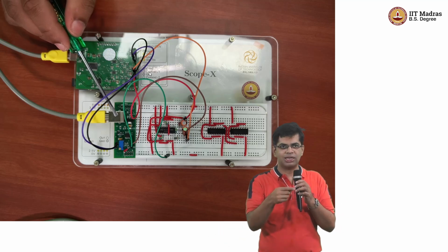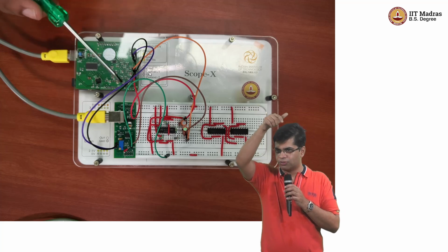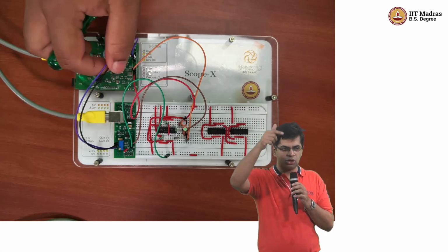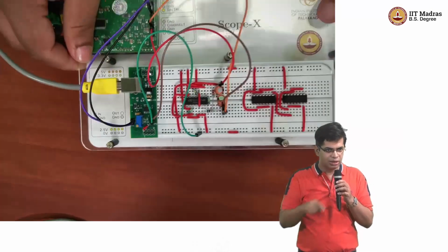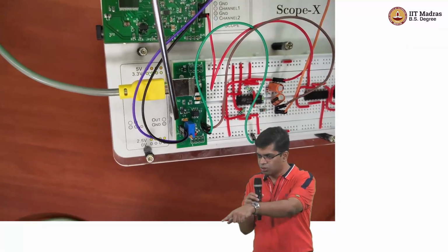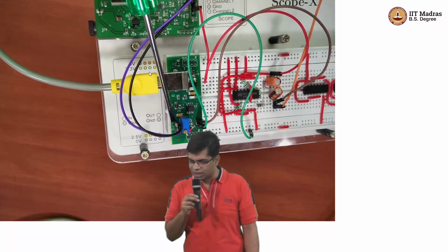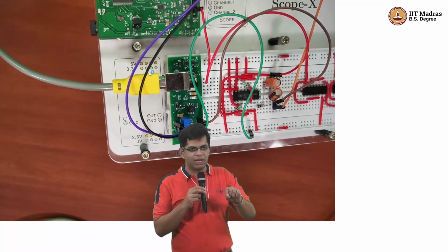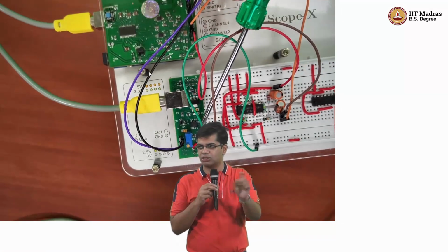When you take the signal from the SIGGEN out, that will be 0 to 5 volts. You give that to the in on the power board. Can you see that? If you read on the board, it's easier to see. On the power board, there is an in on the left side. You give the signal on the in, and then you take it from the out. Has everyone seen the in and the out?